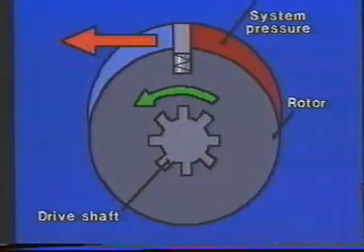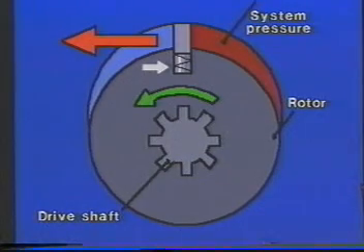Now then, the construction of vane motors and vane pumps is quite similar except for one important fact. In a motor, we must have some means to hold the vane out against the cam rings. Here, we have an illustration of a very basic vane motor. We show a rotor with a single vane being held against the ring by a spring. In operation, the spring would be assisted by inlet oil pressure directed underneath the vane. If this vane weren't held out by some force to begin with, oil entering would just scoot from one side to the other, and no torque or rotation would develop.